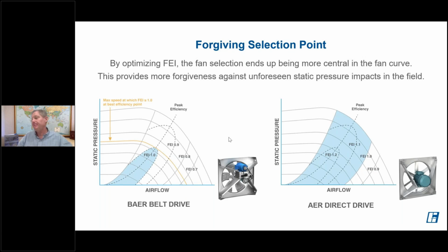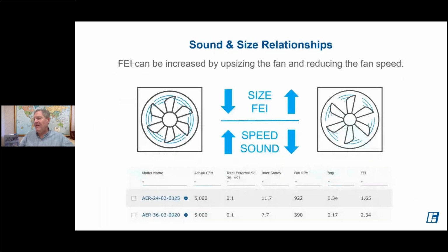All right. And then as far as a sound and size relationship, for those of you who've been doing fan selections for a while, when you have a larger fan, it's going to run slower. When the fan runs slower, it's going to be quieter. Well, the same thing applies here with FEI.